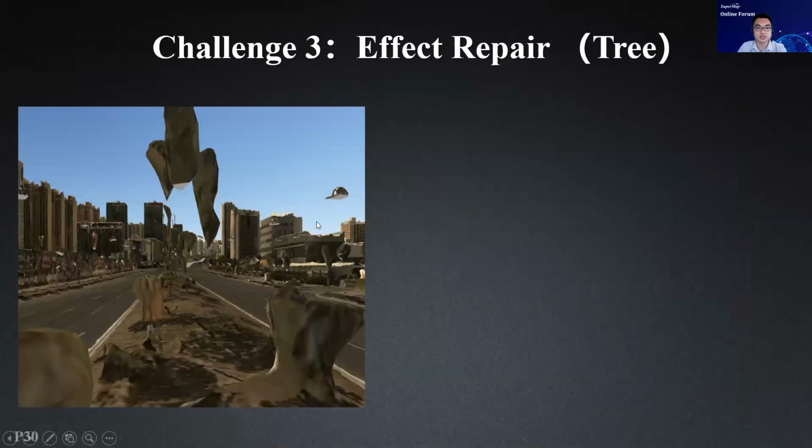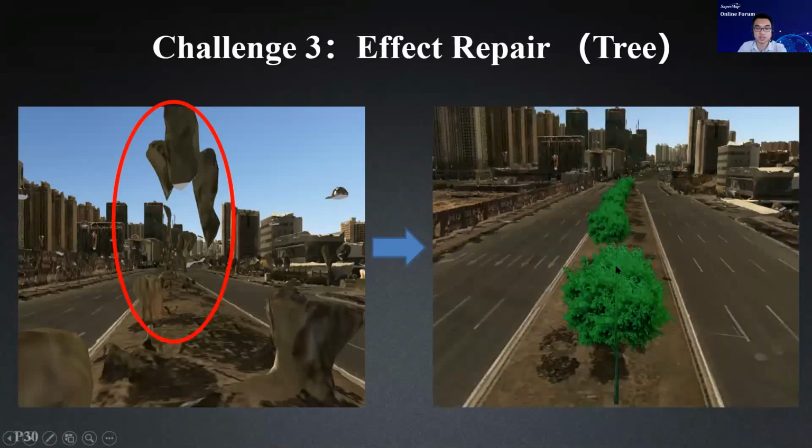And this is an example. You can see we will remove this part and set a new 3D object here. For SuperMap, we provide some default 3D models for the trees or the bus station or the cars. So you can just draw a 3D point here. Then you can do the symbolization, set the different model, set a different object here.